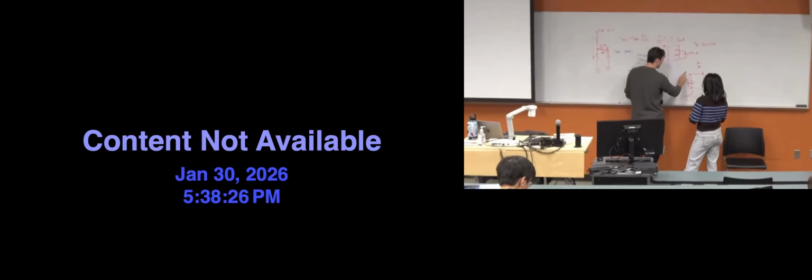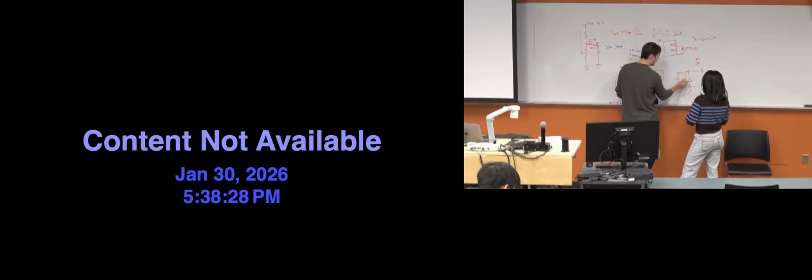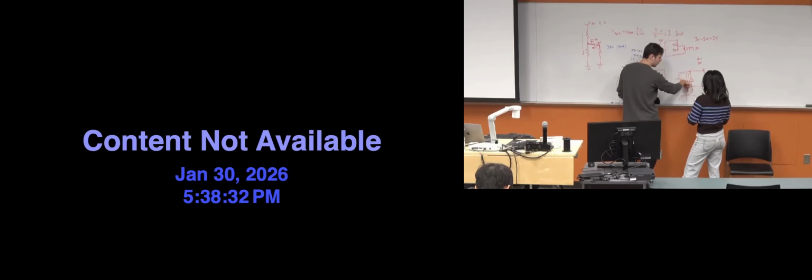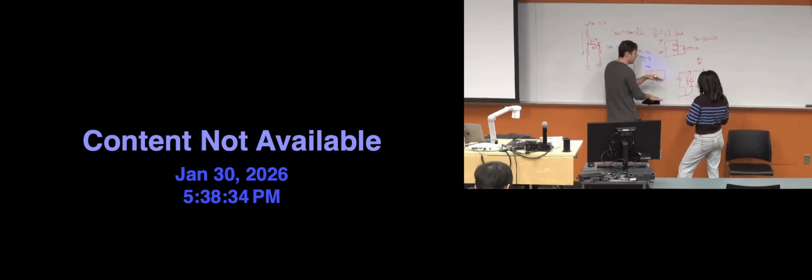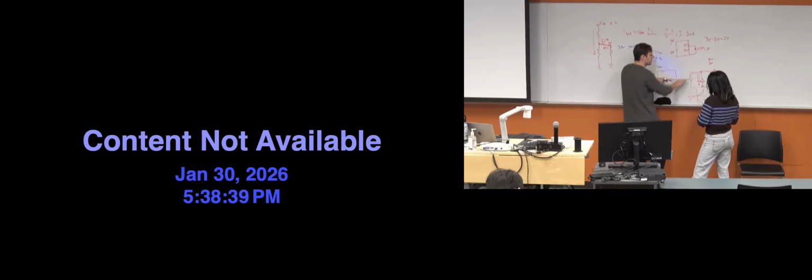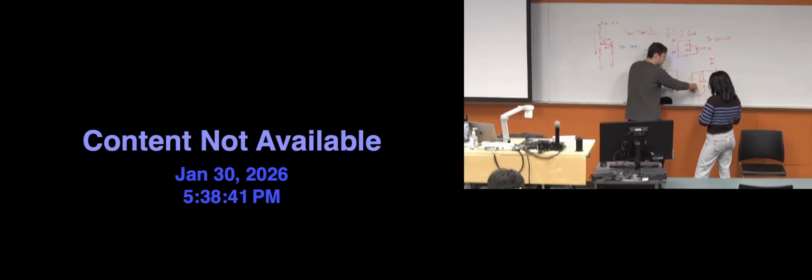You don't want it to get to 6, right? After it gets above 5.5, this is going to break down and allow current to go through. If it gets below 5.5 again, it's going to block current from going through. So it's going to dissipate all the extra current.